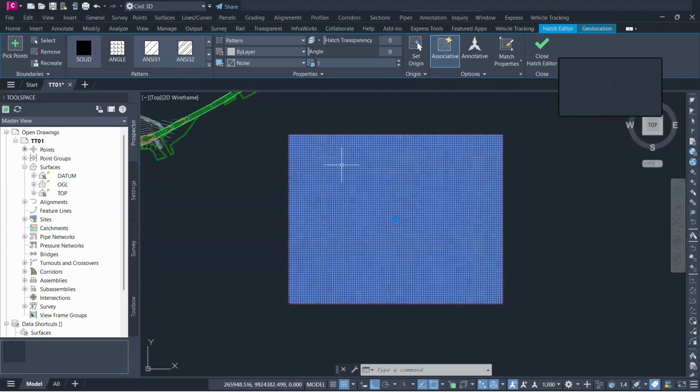So what you will always do, you can lower this surface 5 meters down, and you'll be able to get the new levels at that point. So those ones will be design levels. But what you will notice is that you cannot do this excavation 5 meters at once. So you will do, for example, the job for one day, because you need also to pay people who are excavating based on the volume of material that is pulled out of this area.